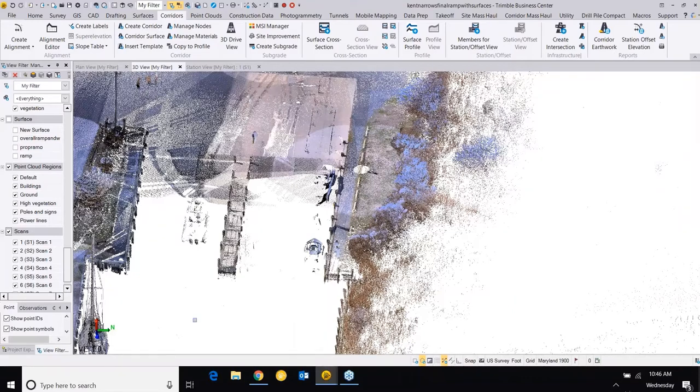The other thing about setting up and being ready for one of these jobs is that you're going to want to look on the NOAA website and see if there's a gauge anywhere. Like we have the Baltimore Harbor up here, Fort McHenry and so on. There are a bunch of tidal gauges up there. If you're going to start up there, I would check into that monument and do a control on it so you actually know where you're coming off of.